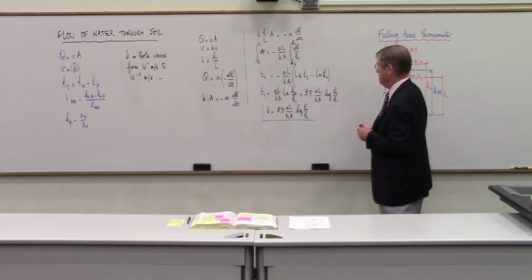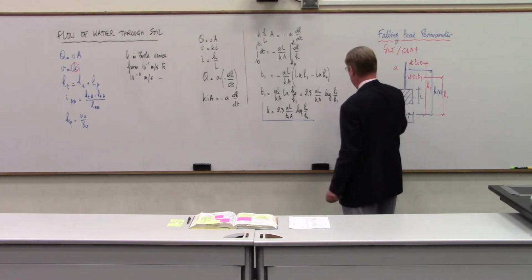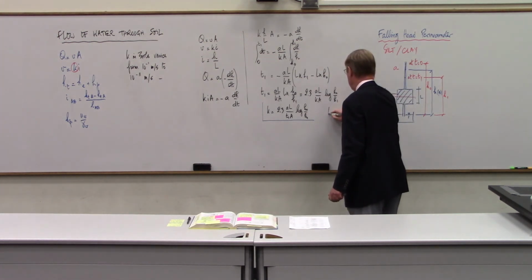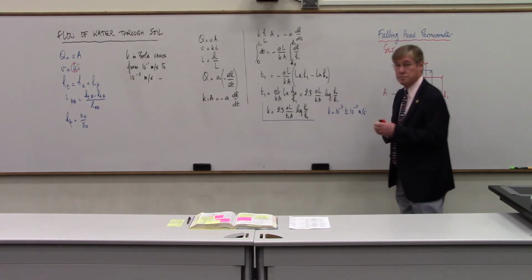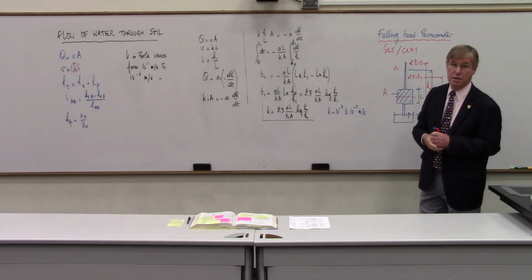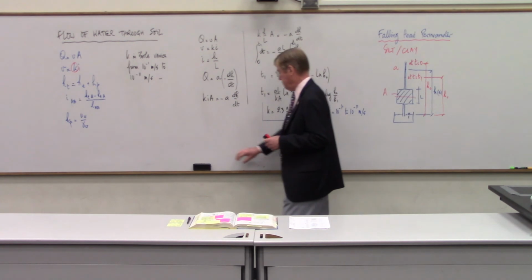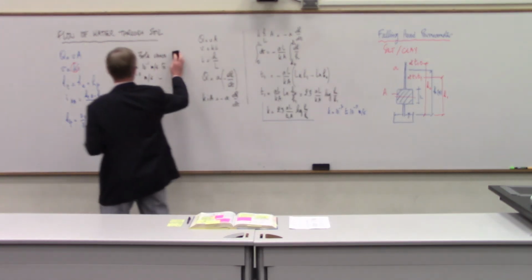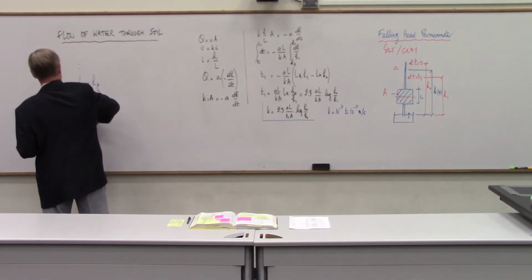And as I said, this is for silts and clays. And so we're talking about K values that are in the range of 10 to the minus 7 to 10 to the minus 11 meters per second. A very, very tiny flow. Having said all this, these are lab tests. We also run field tests.